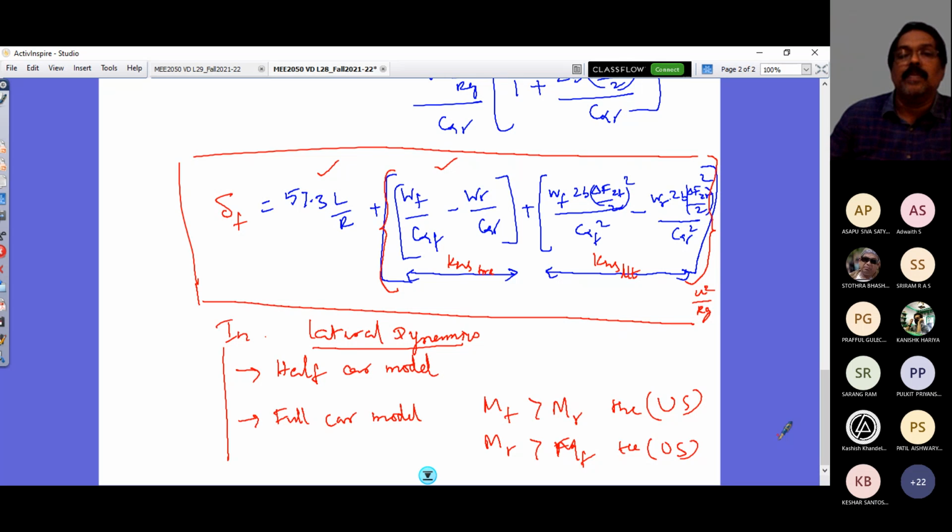From these terms, term 1 here is the understeer gradient from our nominal tire cornering stiffness, which arises from our bicycle model itself. And additionally, you have this term which is due to lateral load transfer. The moment you consider the suspension, the roll is inevitable, and the roll is what causes lateral load transfer from inside to outside during cornering, and that along with the non-linear effect of the tire is responsible for contributing this additional term into our understeer gradient.